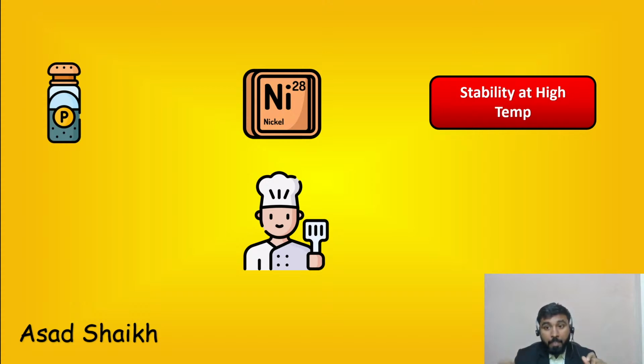Material selection is very, very critical. The third important thing, when it comes to high temperature, is if you select dissimilar metals, if the trim is of a different material than your plug or your stem, each component has its own coefficient of expansion due to heat.